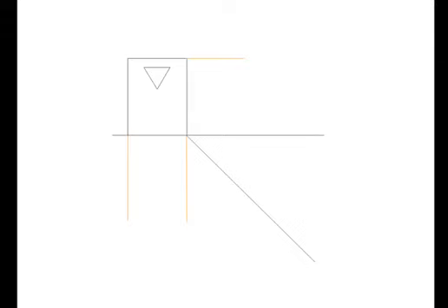Likewise, the lines from the elevation to the plan are going to give us the width of the circle in plan. Now we project down both points of our prism to the plan. This will give us the total width of the prism in plan.